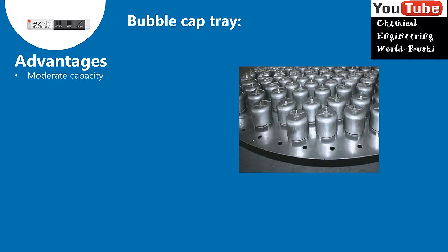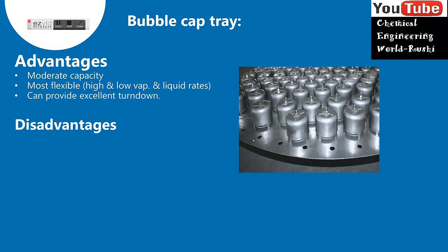Advantages: moderate capacity. Most flexible, with high and low vapor and liquid rates. Can provide excellent turndown. Disadvantages: high entrainment, high fouling tendency, high cost, high pressure drop.